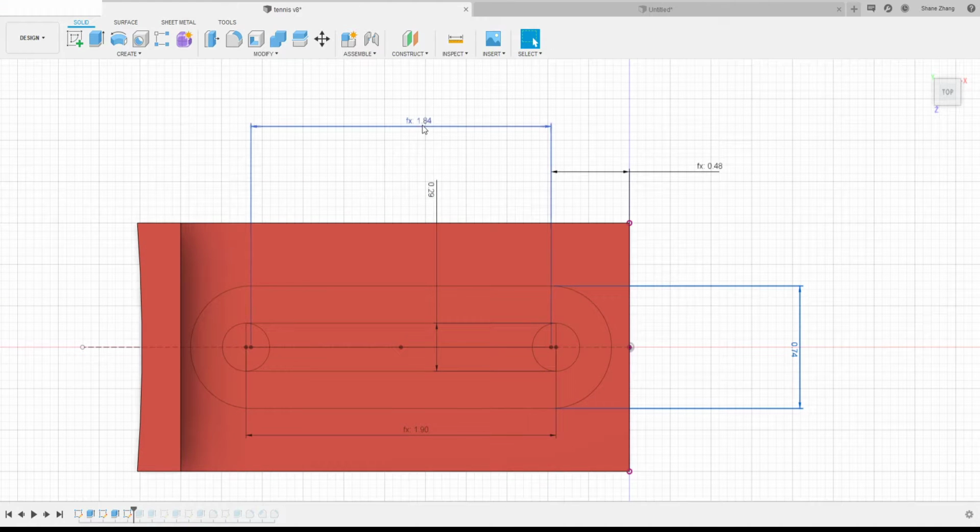And you notice I have an fx here, so it's a function or equation here, and it is because I measured using a caliper from the arc to arc, but when you actually go manufacturing, they probably want to know the center to center distance. So 2.58 is just the measured value. Then I minus D10. D10 is probably this. Let's see if that's D10. Yeah, so this is D10.